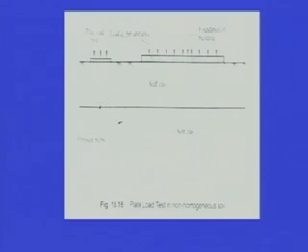Now, this figure shows that if you have two test plates, this one of smaller size and this one of larger size, resting on two soils, with a stiff soil at the top and soft soil at the bottom, then the pressure bulb for the smaller size extends only in the upper stratum, and we will be getting the load settlement behavior of the upper stratum only, whereas the size of the foundation is far larger than the size of the test plate.